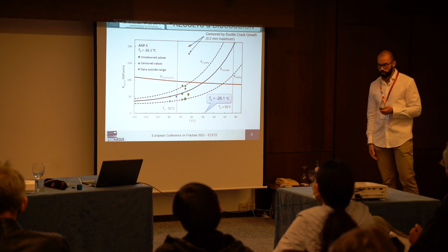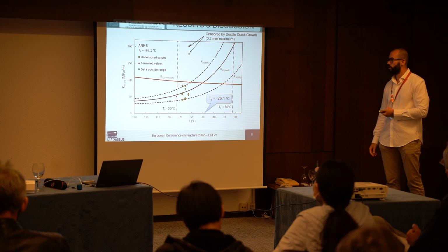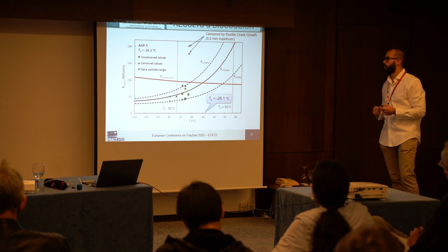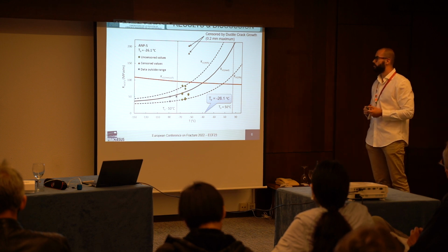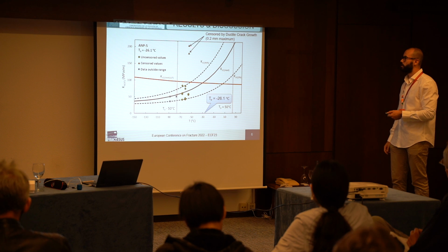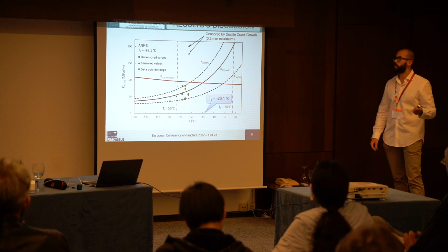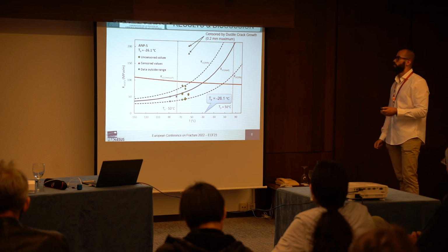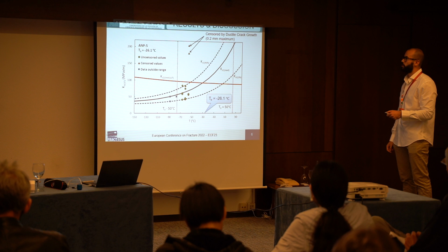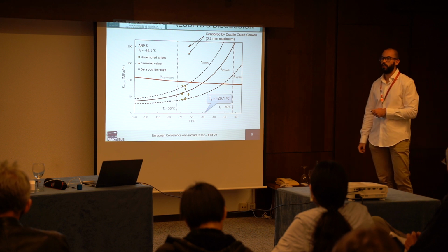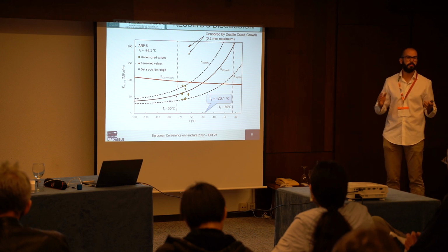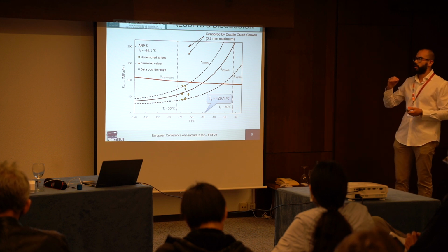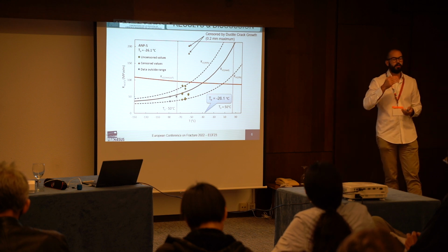You can observe that three values were discarded for the evaluation because they were outside the range of the master curve approach, and two values here were censored in this case by the ductile crack growth because it was larger than the limit that the standard proposes. So these values were converted into the maximum uncensored KJC value of the dataset.